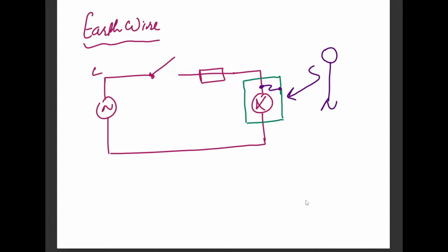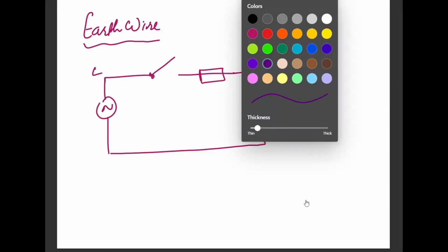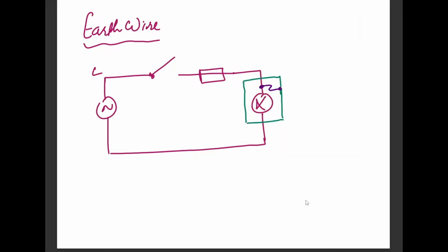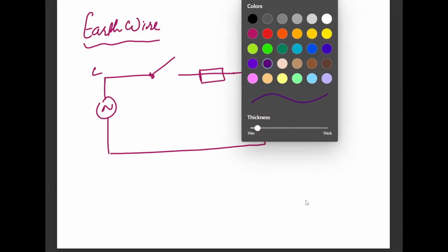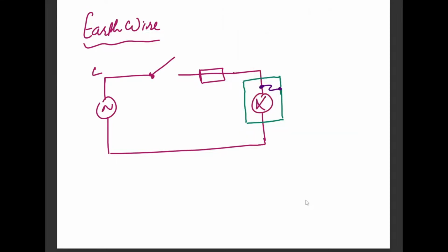So even if a damage situation occurs internally, we can still prevent that person from getting an electric shock. The primary objective is to save the person. The appliance comes second. Okay, so based on this accidental condition, I'm going to deliberately provide the appliance with an alternate path for the current, because I don't know when this is going to happen. So I'm going to connect a third wire with only the body of the appliance and connect it straight to the ground.